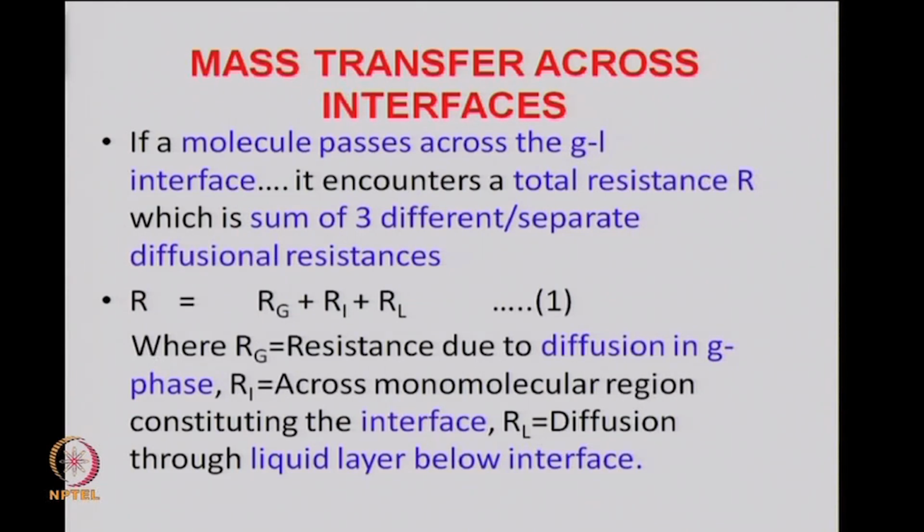The base level case is when the given phase is stagnant or stationary, stationary in the overall sense that there is no net movement visible for that phase. If that is the case, the only way molecules of a certain species could come to the reaction site would depend on diffusion.